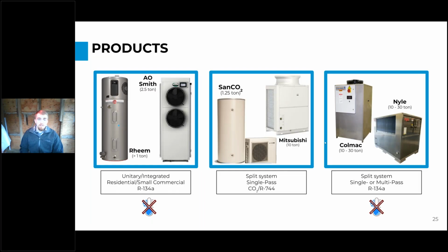And now that we've talked about how heat pumps work and the considerations that you need to make around the heat pumps themselves, we can talk about some of the products on the market. You can see this grouping on the left here. I have unitary R134A residential heat pump water heaters, and some of these apply to small commercial as well. These are what you'll find more likely in your garage in a single family home, or in closets or spaces distributed throughout buildings with small discrete loads, right?